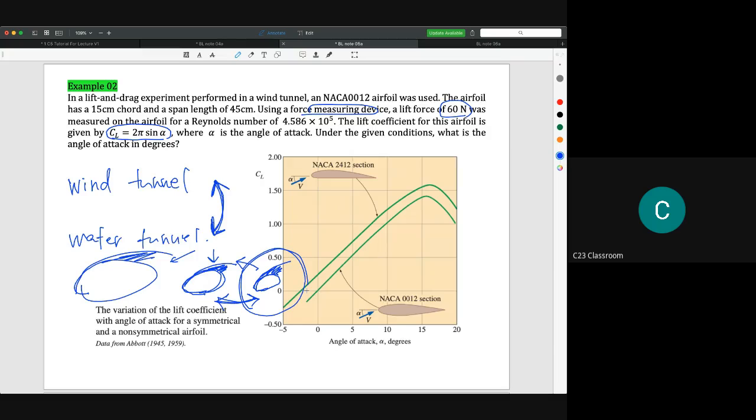the real one. Okay. So at the same time, the problem about the wind tunnel is you need to have a very, very smooth surface, because if the surface is rough, the boundary layer will change. And then it will not reflect the real boundary layer that occurs in full size.